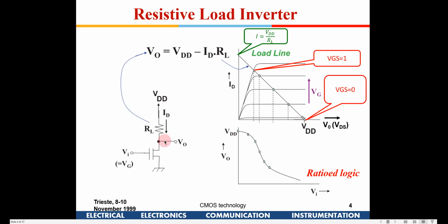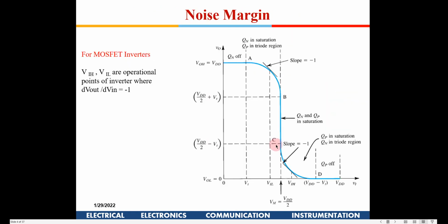Okay, why slope is used for a noise margin? That is just a rough indication that this is going to start, and we have to somewhere mark VIL, right? So slope is equal to -1. It was just taken at a place where this angle out here is exactly 45 degrees, assuming the voltage has started falling down here, right? So that is the reason. There is just a figure of merit which was defined like that. Okay, so a standard datum was set like that. There is no specific reason for that.